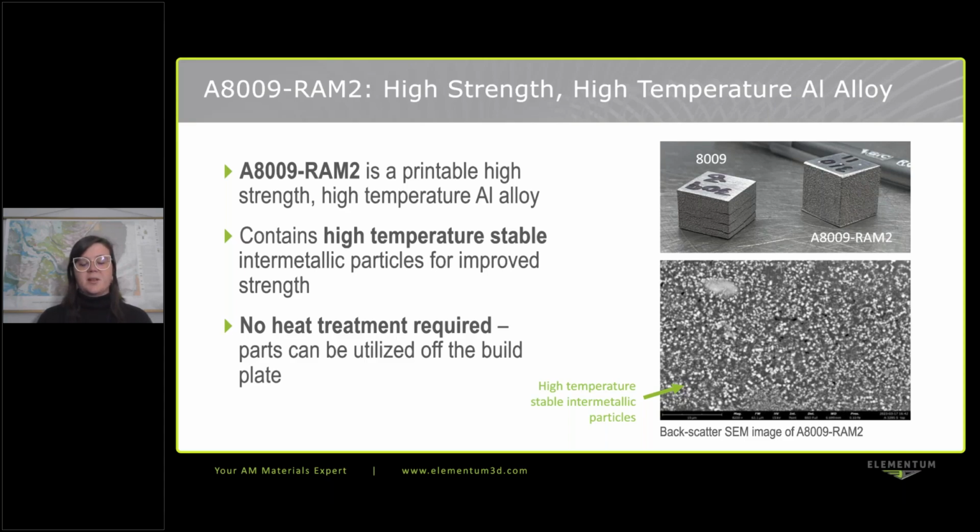And so we were able to eliminate cracking, which in this case was actually more from residual stress than necessarily solidification cracking. But that residual stress basically caused those cracks because of the solidified microstructure. And so with our additives, we were able to change that microstructure and prevent that cracking from residual stress. And what happens is we have all of these little particles, as you can see in that image, that are stable at high temperature, and that gives us that high temperature strength that we're looking for.